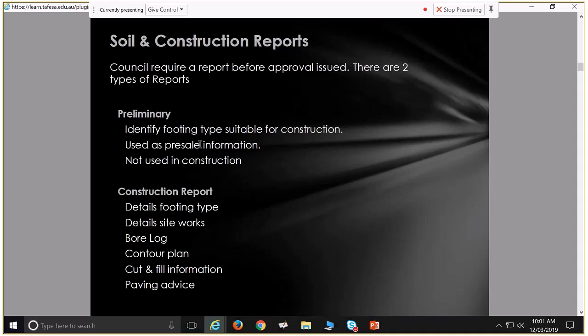So engineers will detail things like that, and they'll also look at the trees and sometimes suggest removal of trees as well, or specify removal of trees to say, look, you can't have that tree this close to the building, well, not with the footing type that you've chosen to use. So you have to get rid of that tree as well.